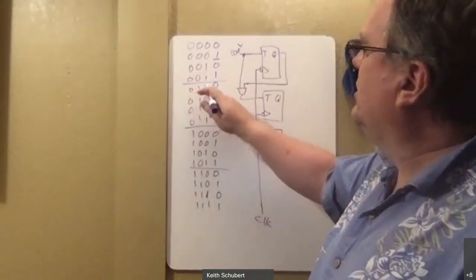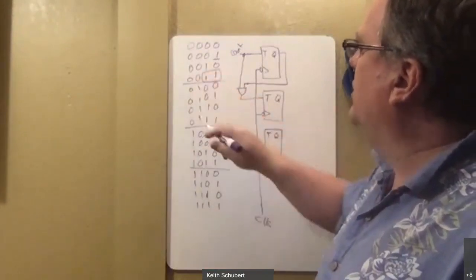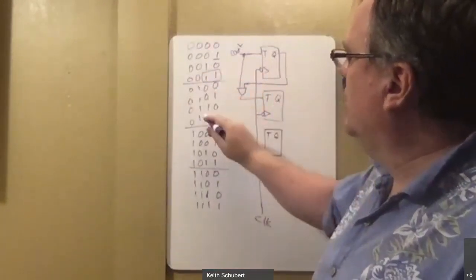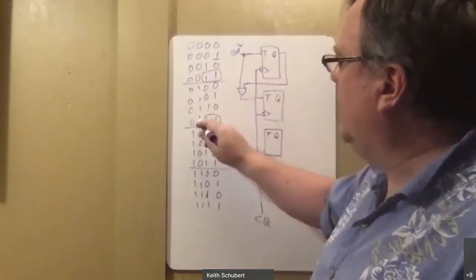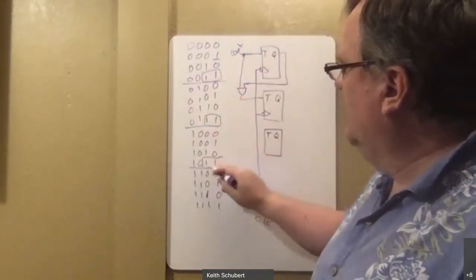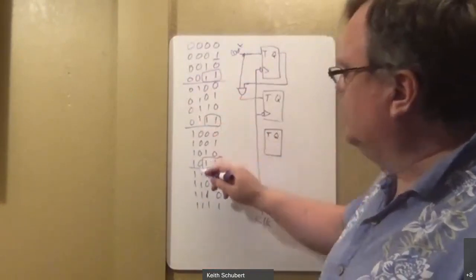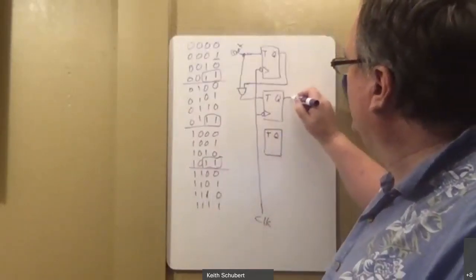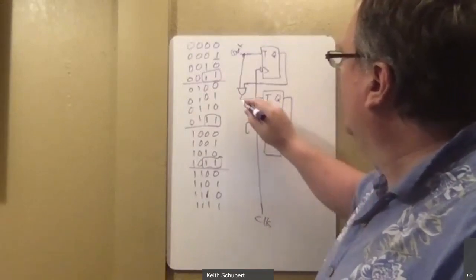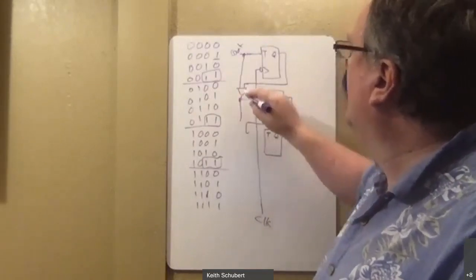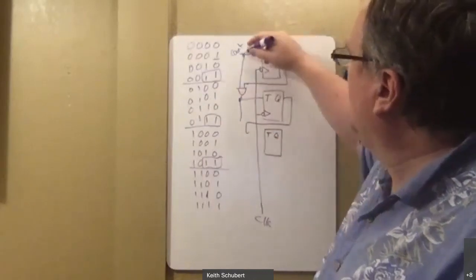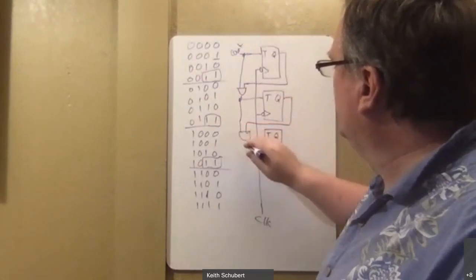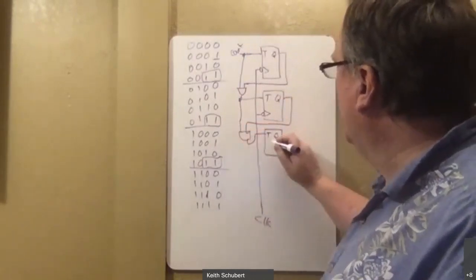All right. We've got up to the second one transitioning. To get to the third one, I want both of these on, and it had better be a count to toggle the next one. Both ones on and the count comes in, it toggles. So this one needs both of these on. So this one, that one. That's my first AND. Here's my second. So I feed them back together and put that into toggle.